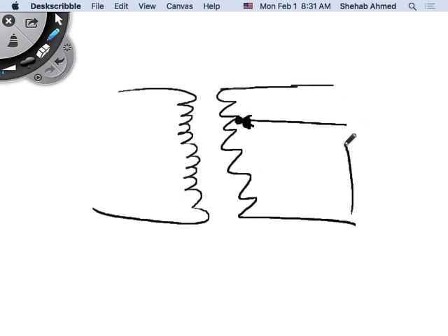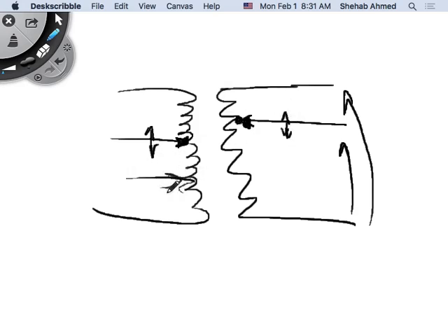Here, the voltage that you get here is less than the voltage that you have here, right? And you can do the same thing with the primary side as well. So this can be moving up and down, for example, or you can have many of those fixed, like we have in this transformer. You have many of these connections that are fixed, or you can have something that is motorized and moves, right? So it can be an on-load tap changer, or under-load tap changer, meaning it can happen in real time while the load is connected.